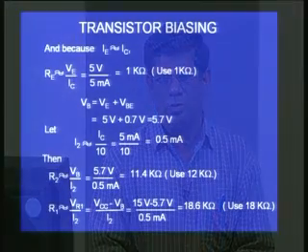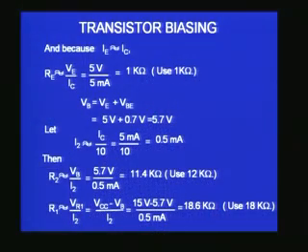So R1 R2 for these two conditions will have to be both small as well as large, which is not possible. Therefore we should try to get a compromise value. The compromise value in general is assumed corresponding to an I2 value which is about 1/10 of the IC value. This is a thumb rule, a simple guideline for the design.